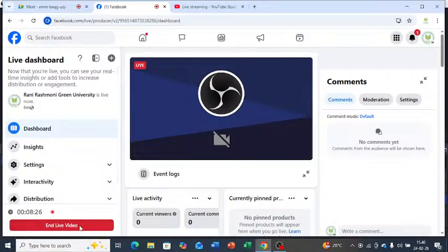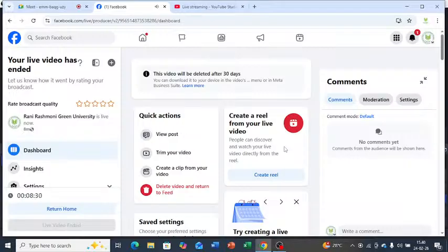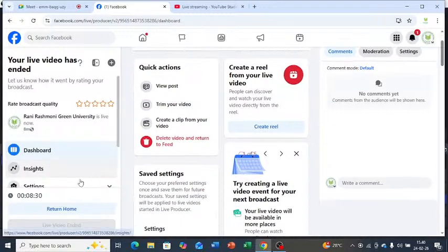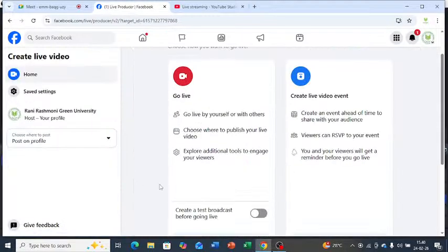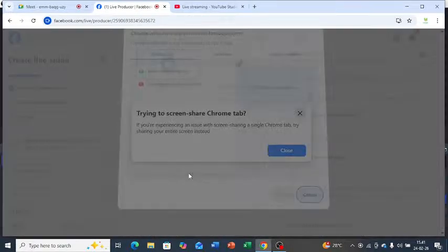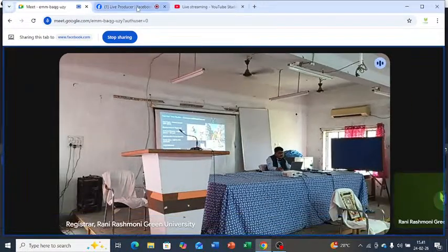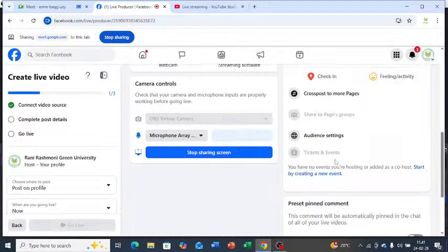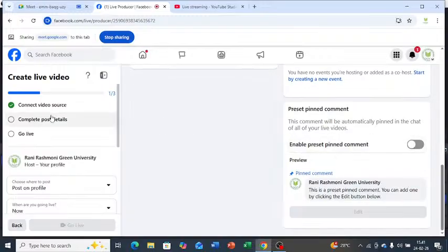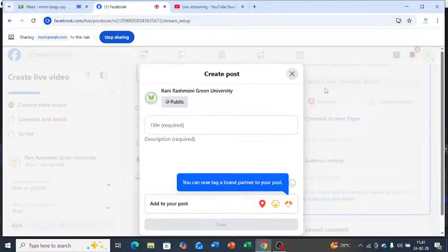Now there are a few more advantages of these, like I showed. One is the horizontal drive, and there is no clamp. So it is an endless drive. If you turn the drive, it will never end. It can move 360 degrees also. So this is called endless drive. You can directly insert a pen drive to transfer data. You can also insert SIM cards to get internet on board, and you can measure the height of the instrument from the ground through laser plummet.